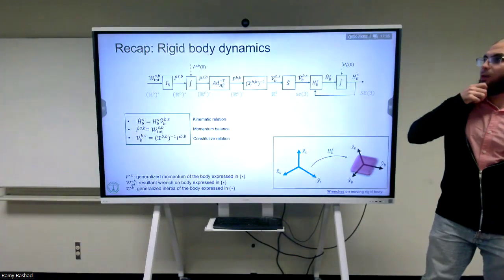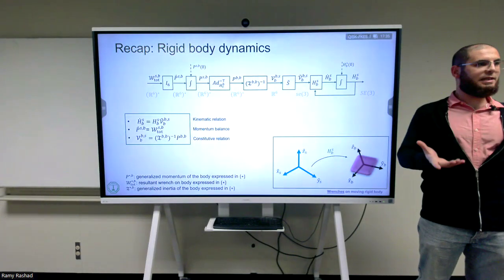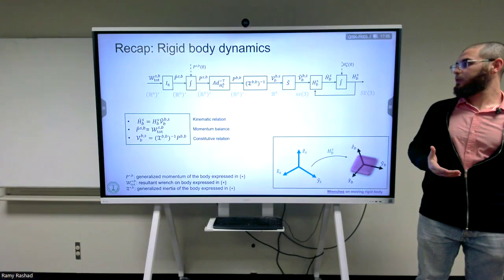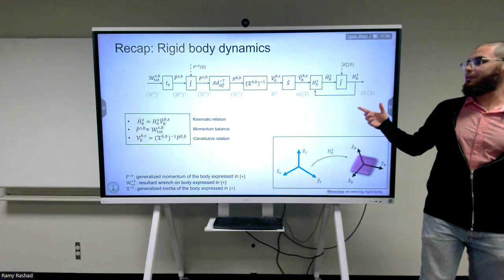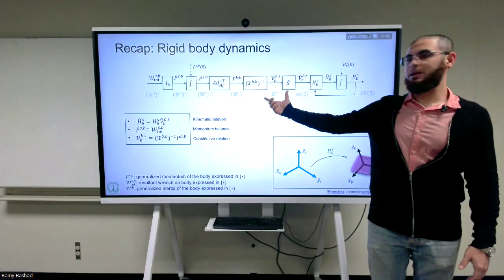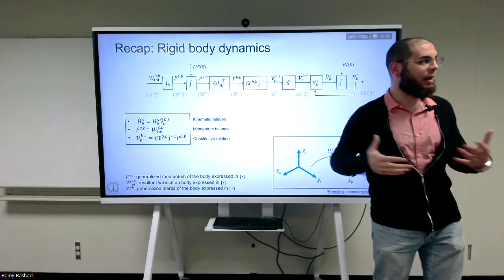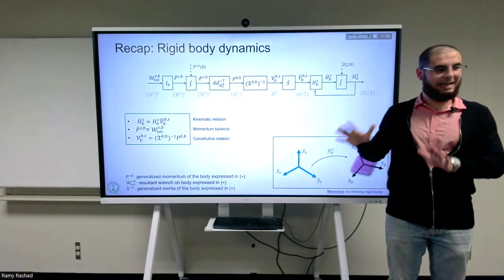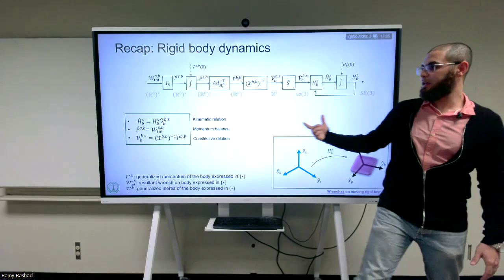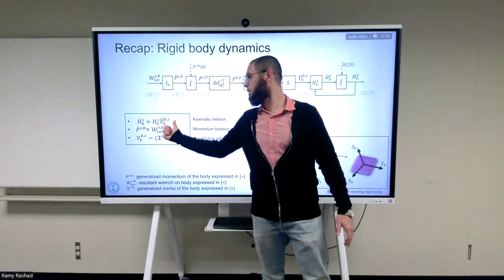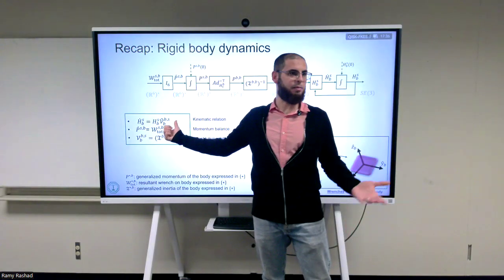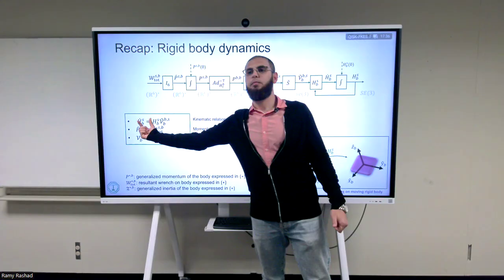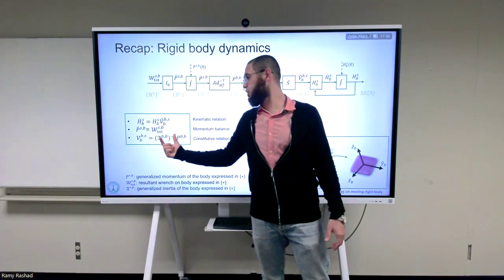And when we look at rigid body dynamics, using these tools that we have, working on SE3, everything that we have here is simply 6 numbers. How can we start doing the same, so mimic the same nature? Exactly what you saw there will be here. You have a kinematic relation between the generalized velocity, being the twist, and the pose of the rigid body.